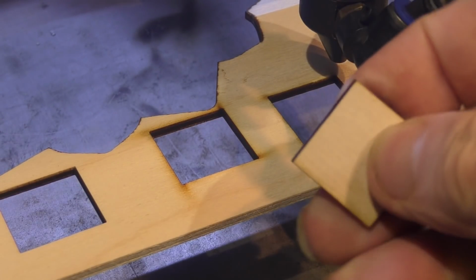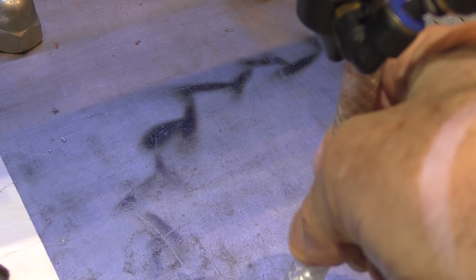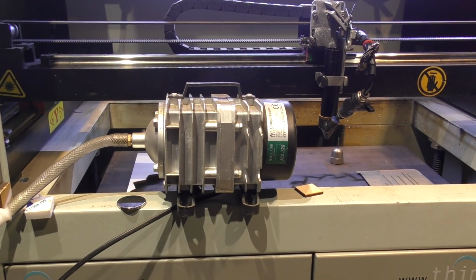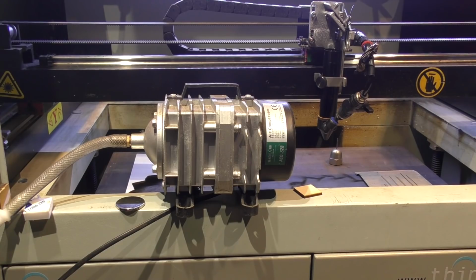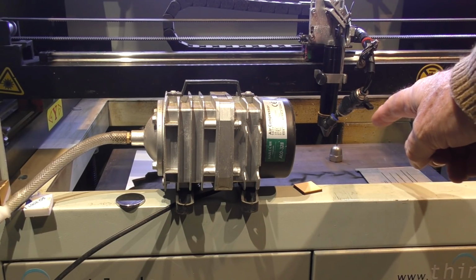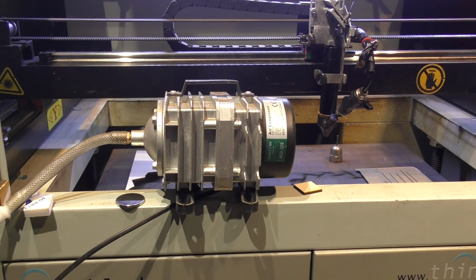Well, I've got a pretty clean cut there at whatever flow rate that is. And the answer is about 7 litres a minute. And that's using one of these little pumps, which is capable of delivering maybe 40 litres a minute at 3 psi. It's not controlled by the psi, it's now controlled by the restriction that I've got on my restrictor here. I'm controlling a flow rate. I'm not controlling a pressure.